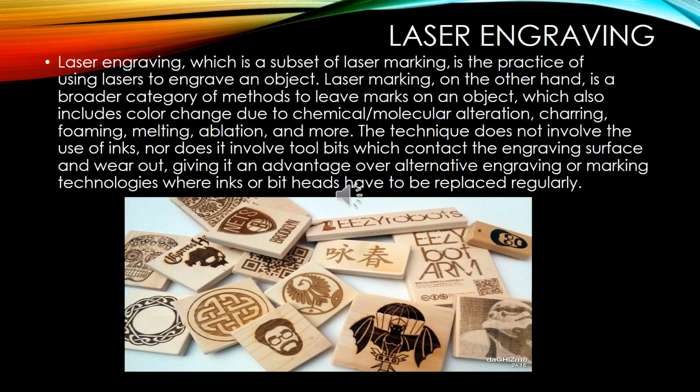Paper masking tape is sometimes used as a pre-engraving overcoat on finished and resined wood, so that cleanup is a matter of picking the tape off and out of the engraved areas, which is easier than removing the sticky and smoky surrounds.